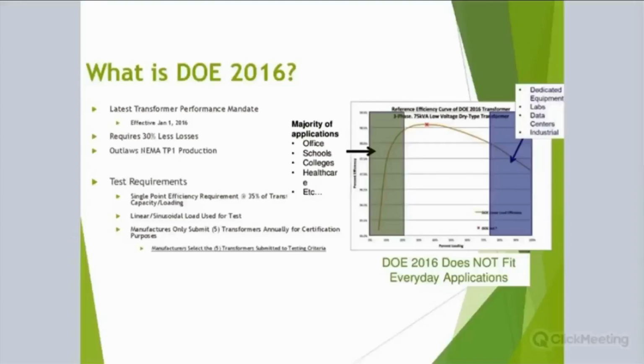The unit with 850 watts of energy loss could still meet the mandate. However, the one that's 150 is just ultra high efficient. So that amount of difference could save you a good bit of money because that loss is 24/7, 365. And whatever your electric rate is, you can do the math and determine how much that loss is costing you.